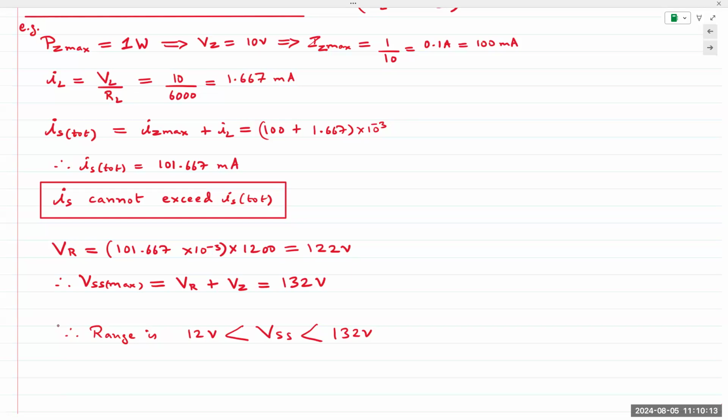So you have a range of Zener diodes, maybe at 10 volts. One of them might be 0.25 watts, and then half a watt, 1 watt, 2 watts, 3 watts. The higher up you go, the more expensive it gets. So if you have a 2 watt Zener, a 1 watt Zener, and a half watt Zener, then you figure out what your system requirement is, and what is the least expensive option that could fit your system.